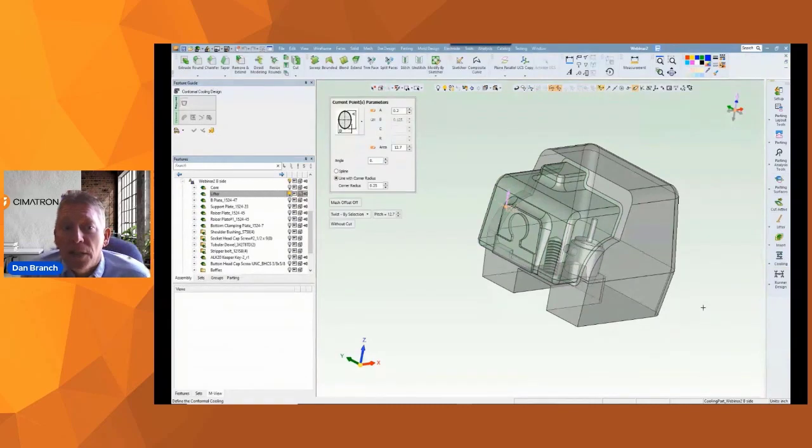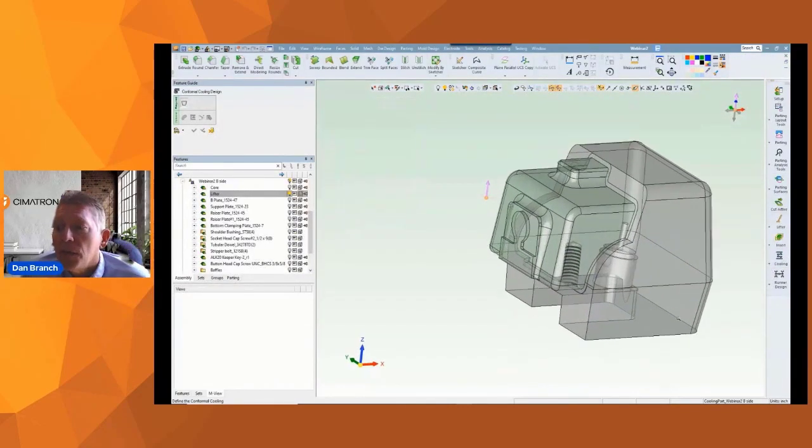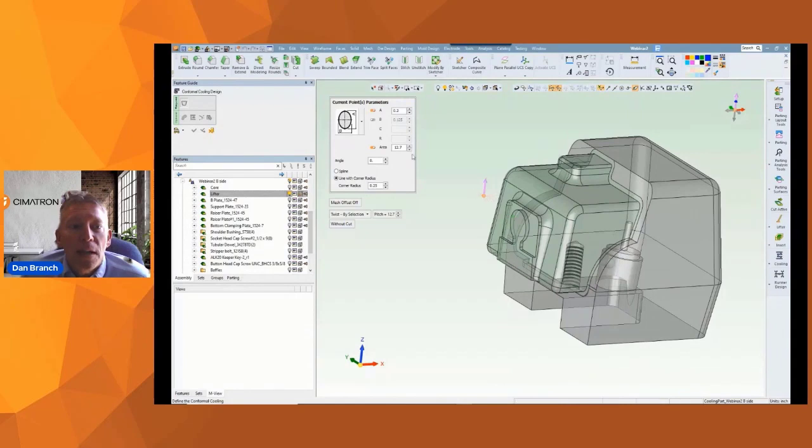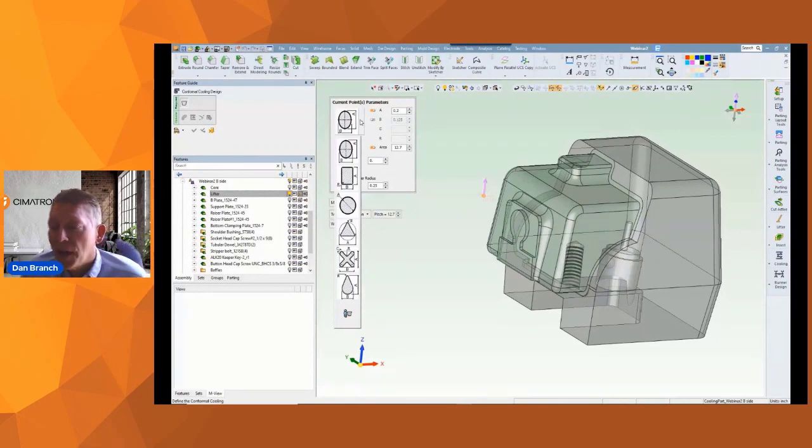But what about designing the conformal channel? Just how is it done? Cimatron has a function to show exactly that. I want to show some options here. Unlike the cooling circuit function, the conformal tool allows for a variety of waterline shapes. And these are all proven cross sections that provide a lot of surface contact with the steel to remove the heat. The other important feature of shapes like this is they minimize the downward facing area. When you're 3D printing, downward facing areas need support. And creating support structures inside water channels is not really a good idea, so we want to avoid that if possible.